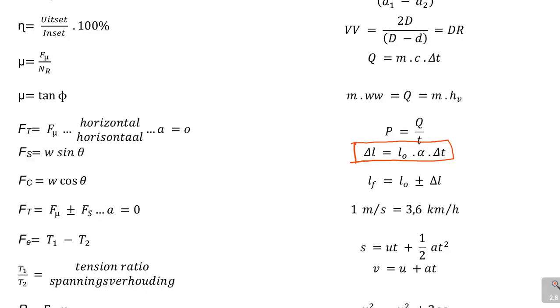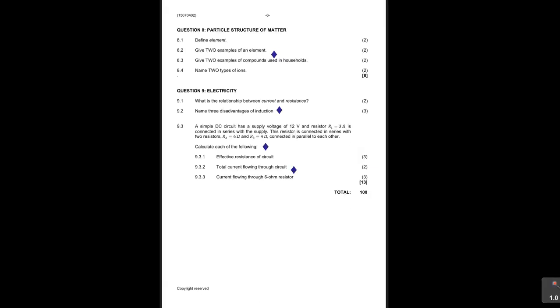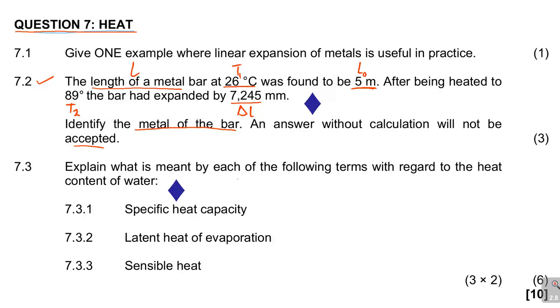change in temperature. So if I can use this formula and write it to say, I'm just going to work it here to say the change in length is equal to L0, and then multiply, they use the dot, times that alpha sign, the coefficient of expansion, and then times the change in temperature.